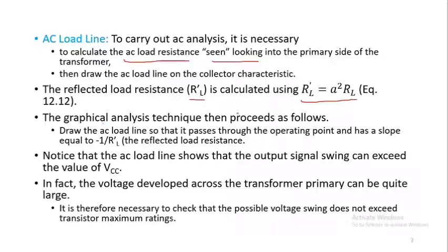The graphical analysis technique then proceeds as follows: draw the AC load line so that it passes through the operating point.